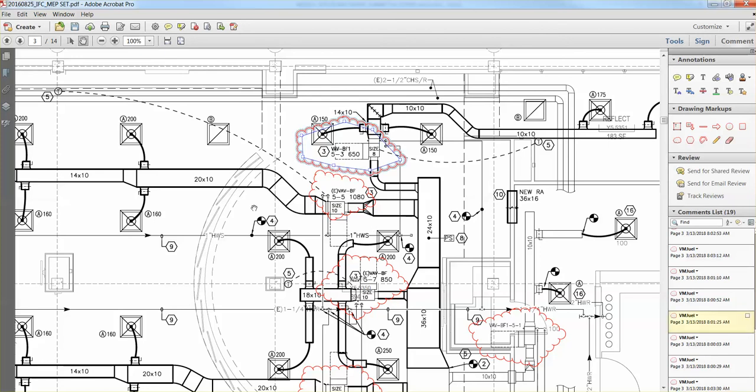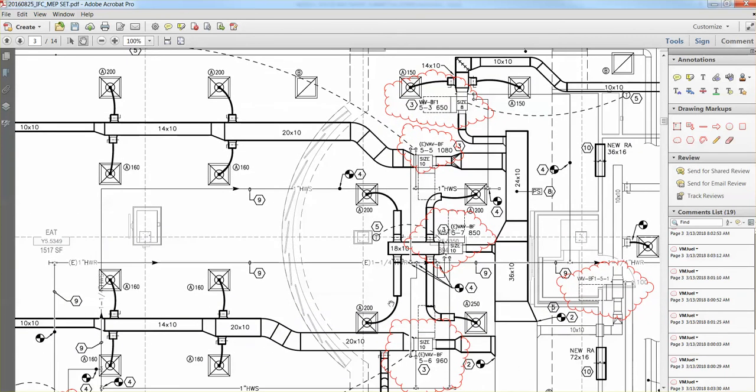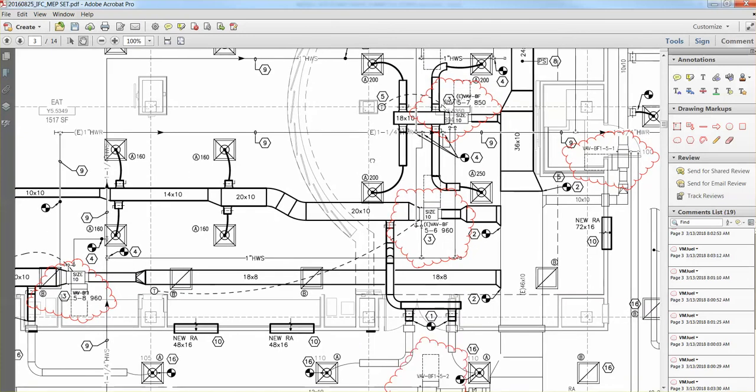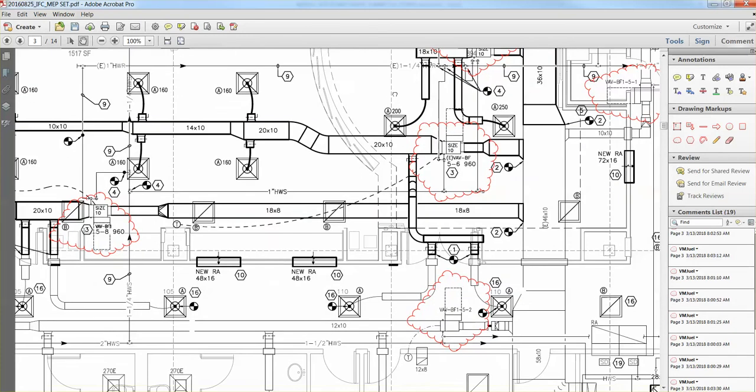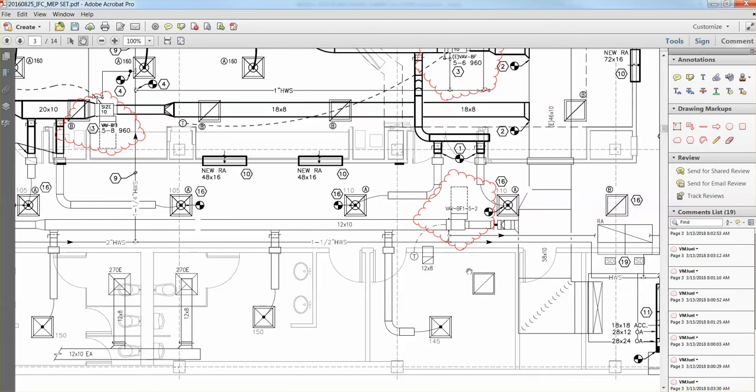So on this particular one, let me find one that's far away. Are they all pretty much general open rooms? Yeah. Okay, here's another one, BF2. If you look, the T-stat's in this room. It's not in the hallway. Even though I can't find a hallway thing, you're going to have to RFI to find the room number of this so you can label this thermostat correctly. So anyway, back to the submittal form.